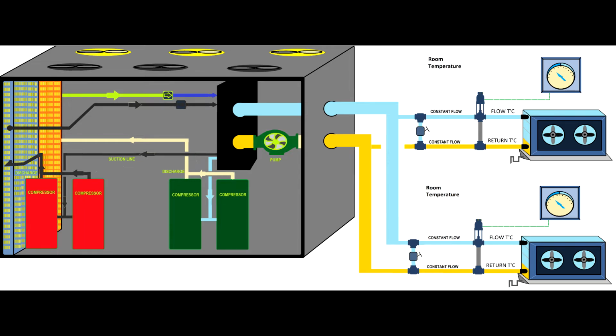And if half of the system is paralyzed, like 2 of the 4 compressors are not running, you lose half of the capacity, and then the process is compromised.